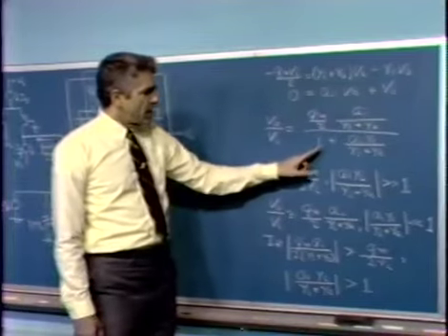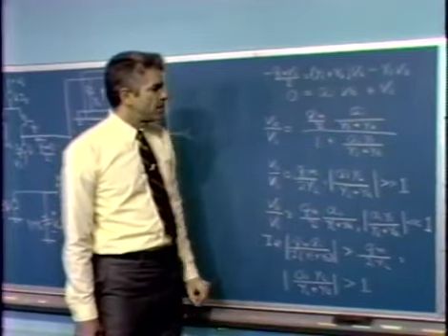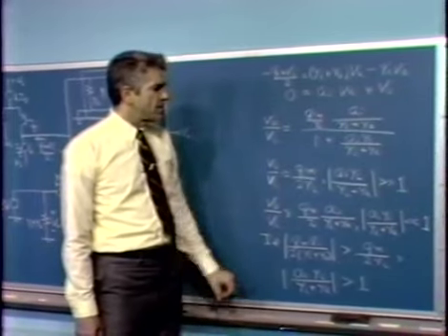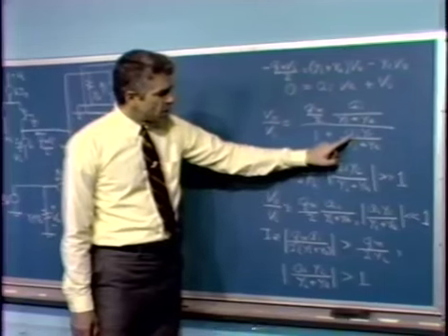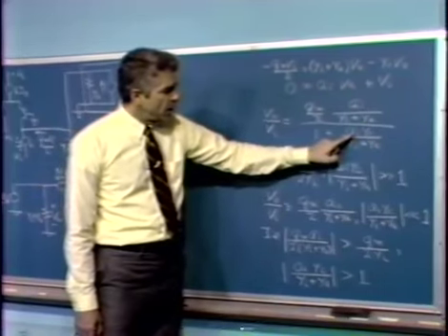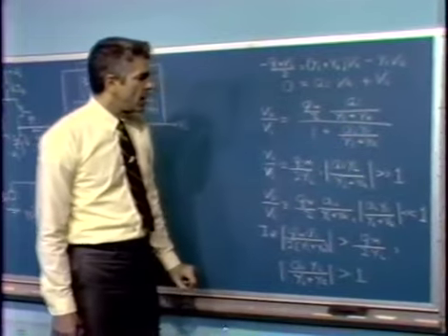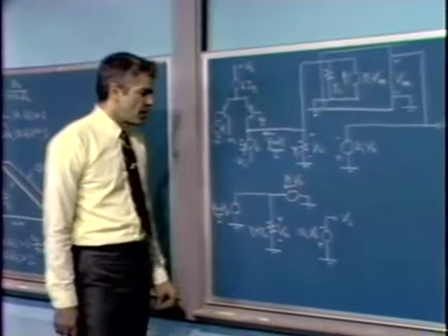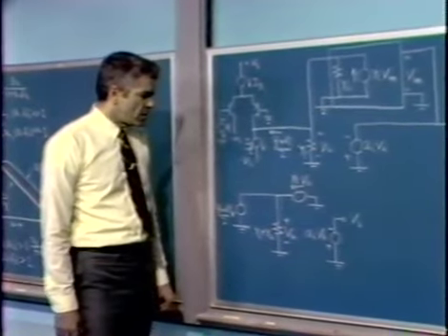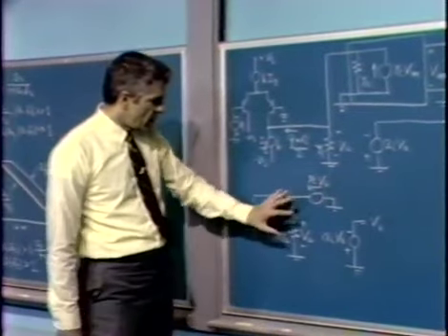The denominator has a very familiar looking feedback form, 1 plus something. It'd be very reassuring if that something were minus the loop transmission. So let's consider the quantity A sub I times YC over YI plus YA. Well, as we suspected, that's precisely the negative of a loop transmission, and in particular, it's the transmission around the minor loop. Let's consider the minor loop.